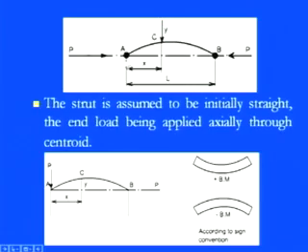In front of you is the diagram I described in the previous one. This is the strut, and these two extreme joints are the pin joints, the rounded ones A and B. Axial forces are acting, and since it is in compression, we have a deflection with a curved shape. At a distance x, the deflection is y, and the total length of the strut is L.